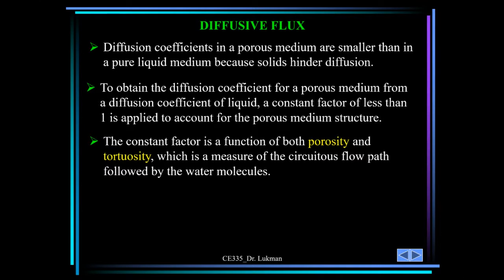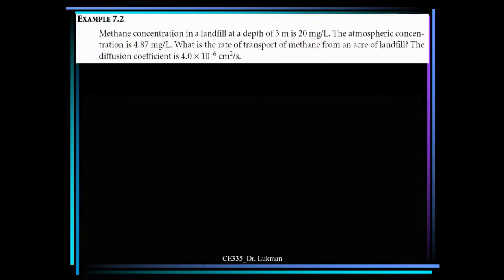So that creates an irregular, tortuous path through which liquid can flow. Okay, so all this affects the diffusivity or the diffusion coefficient when you have porous medium.